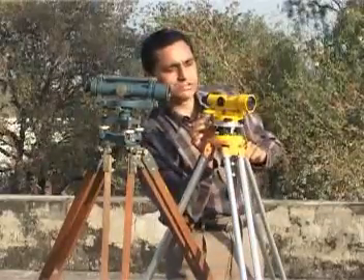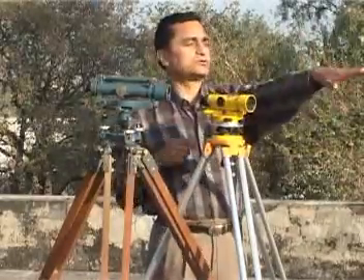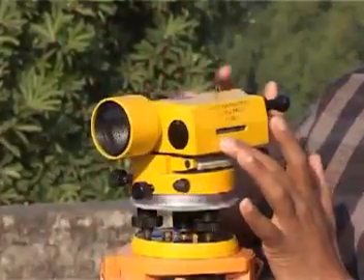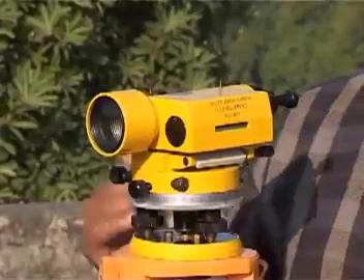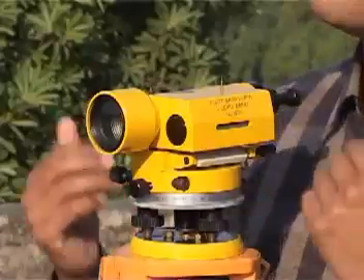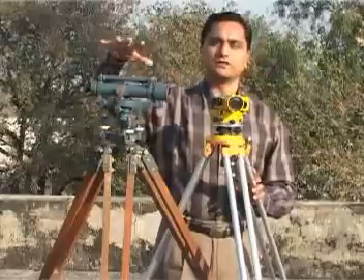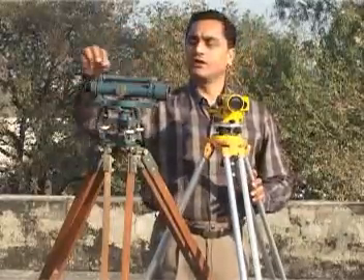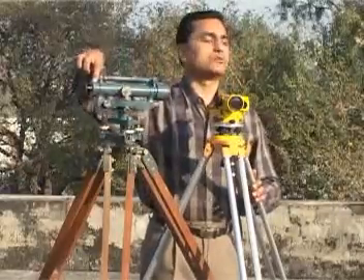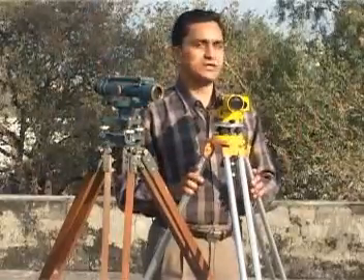Once I focus it, I want to level it. So to level it, I will use the tilting screw. Using the tilting screw, my line of sight is horizontal and I will take the observation. The problem in this case is, the moment I change it, the leveling will change, because we have leveled it only in one direction. So we use this for fly leveling, where we can do it fast. While in the case of the dumpy level, this instrument here, once it has been leveled, you can use it anywhere. Everywhere the line of sight will be horizontal. So wherever the staff is kept, I can take the observations there.